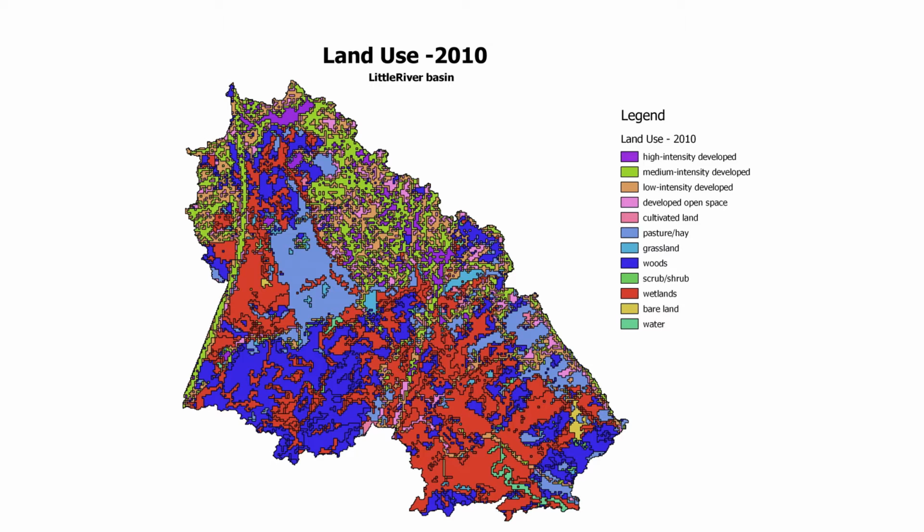Overlaying these maps results in a single map with thousands of tiny polygons of various parameters, and the GIS software is able to come up with the acreages of each of these tiny polygon areas. As you might imagine, it'd otherwise be impossible to ascertain the acreage of, say, low-intensity developed land with hydrologic soil group C within Little River Subbasin X. This is, however, a very necessary step in developing a single runoff curve number for each subbasin. Thank you, GIS.